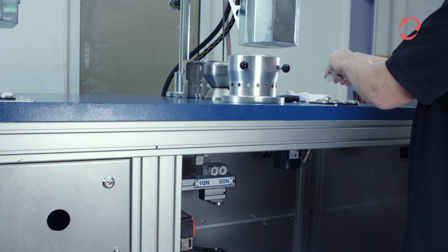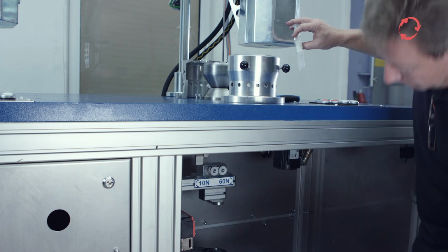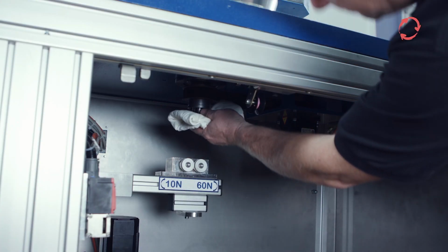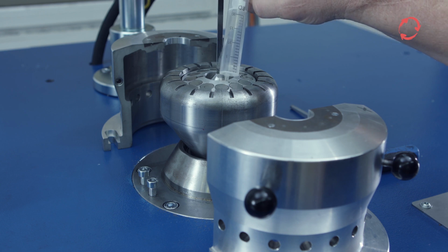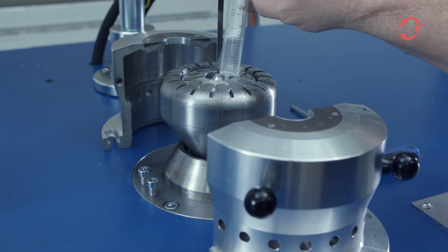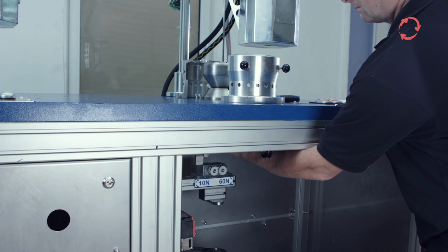Then clean the thread guide channels with acetone. The acetone has to be injected with a syringe into the thread outlet. Keep acetone about 1 hour in the winding head before blowing out. Keep a cleaning cloth pressed against the head on the bottom end. Ensure that no acetone drops on the sensors.